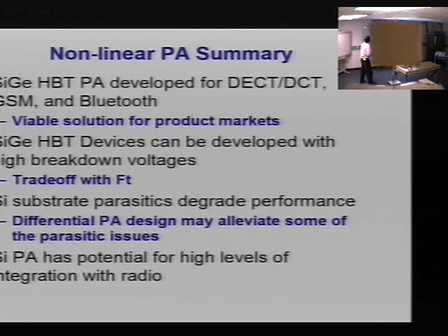So I really believe, from what we've done, that silicon germanium really is a viable solution for nonlinear PAs. And like I told you, even at National, we developed a process for HBT devices with high breakdown voltages. You need that swing. And the substrate parasitics can really have an effect, and one would have to think about a potential differential PA with a balun.